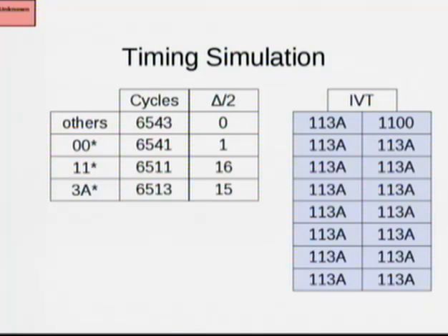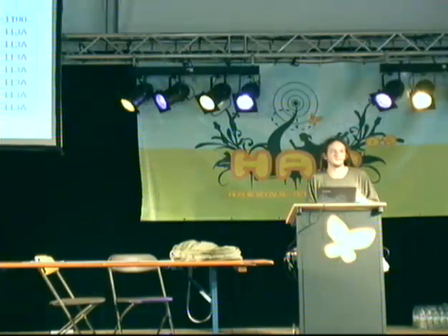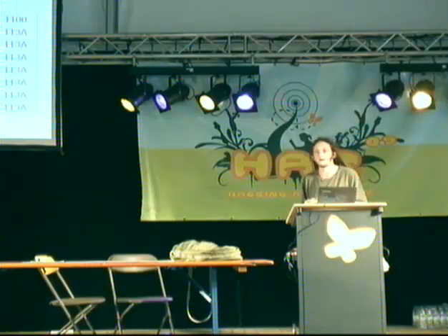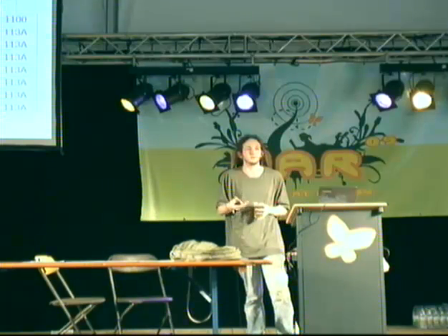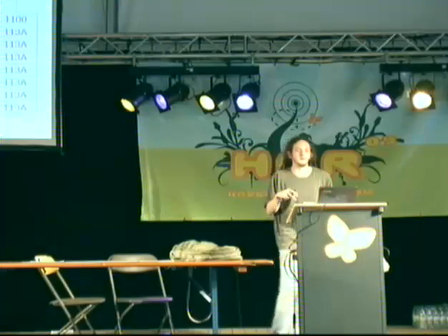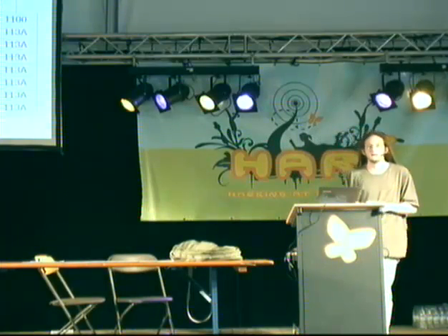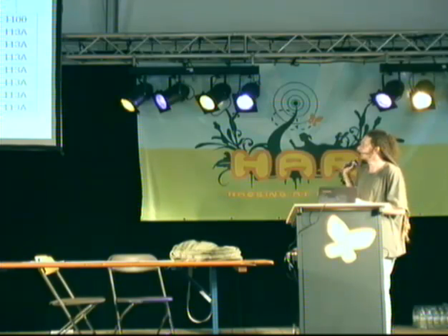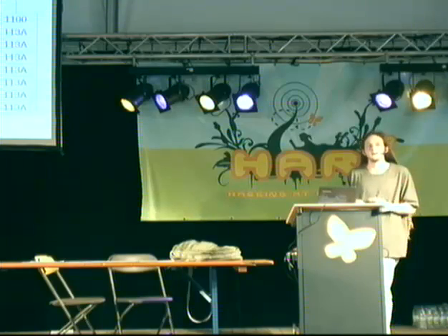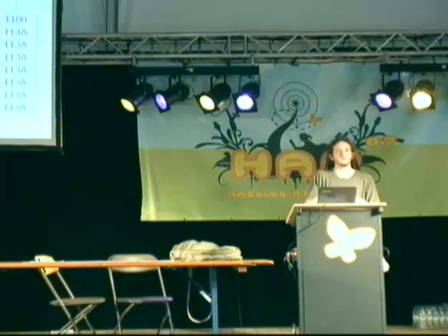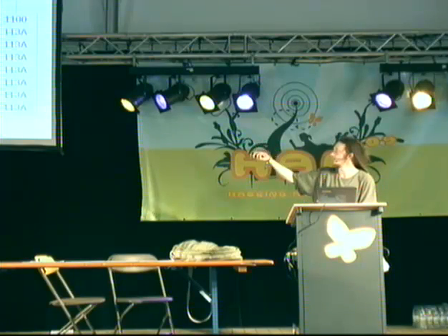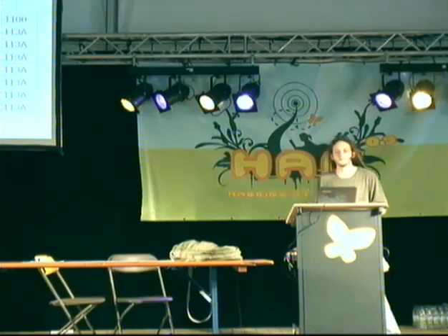So if you were trying to brute force this, you could do it in very few attempts by assuming that the startup word, this 1100 here, always points to the beginning of flash memory, which on this chip is 1100. And then you just start counting up the other word until it latches in, and that will break any application that doesn't, say, rely upon interrupts for power efficiency or for button inputs or things like that. If you have one that does use those, then you can guess which words will be outside of this pattern. And there are different strategies for guessing it. In a full application, guessing it becomes infeasible without the timing attack. But if you have an amateur programmer, or if the only purpose of writing the program is to test the timing of the password routine, then it becomes a lot easier.